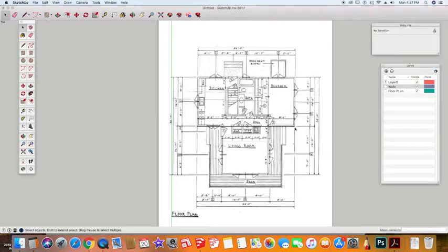And we know that this is 32 feet wide. And if we go here to the extension line from the corner, we can see that there's 8 feet and 8 feet, which makes 16 feet. So we could actually go ahead and make this box here to create our 16 by 32 foot part of the square. So I'm going to click the pencil tool, and I'm going to mouse over my line until I get to that end point.